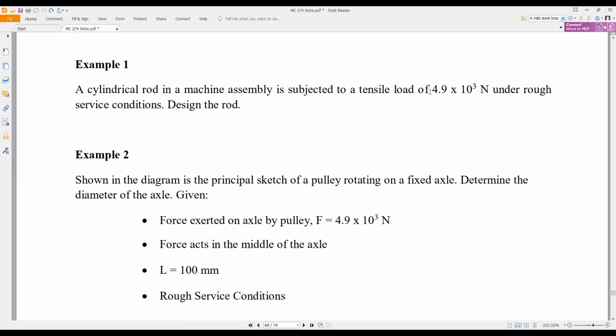If we are assuming a material, we need to determine the ultimate stress in the material and then decide on the factor of safety we are using for the design. In that case, the stress buildup in the material should not exceed the allowable stress. Here, this is tensile loading with axial forces, so we are going to have a direct tensile stress in the material.